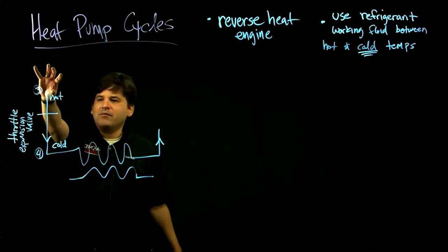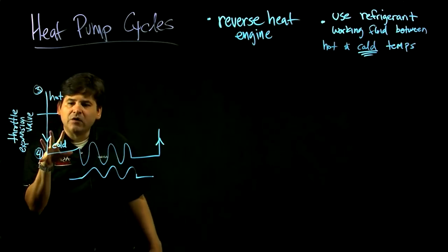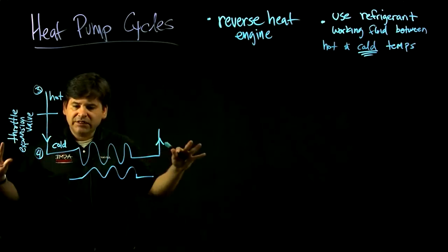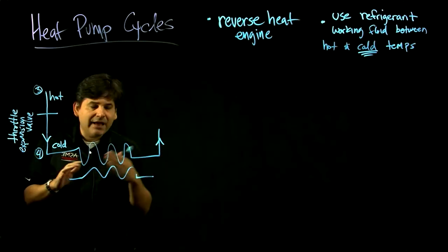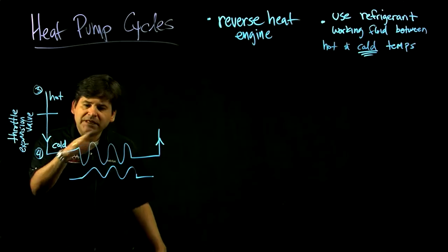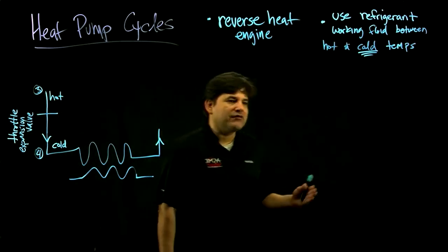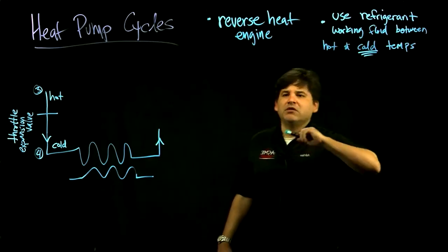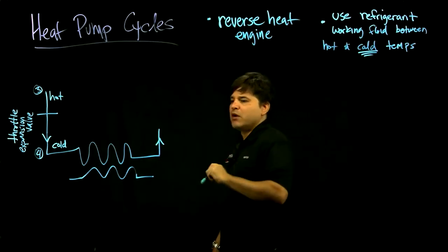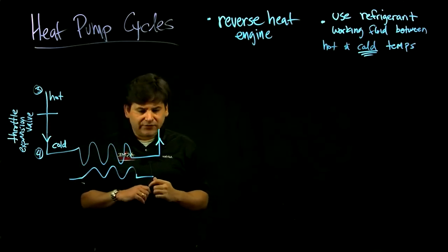You can have a high pressure here, high temperatures here, and then if you expand it through this valve, the pressure decreases and the molecule's response to that expansion to low pressure makes it really, really cold. It's a special molecule. Not all molecules do that. A lot of them do, but refrigerants do it very well. They have an extreme response to this expansion in the throttling valve.